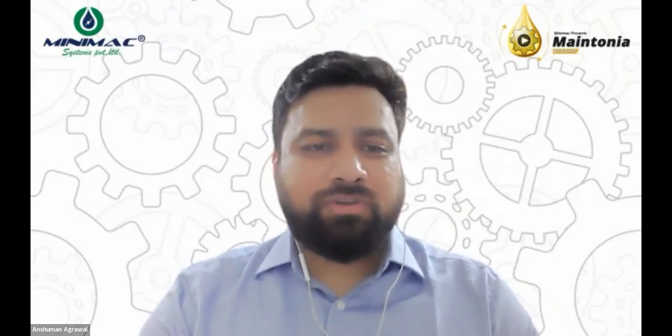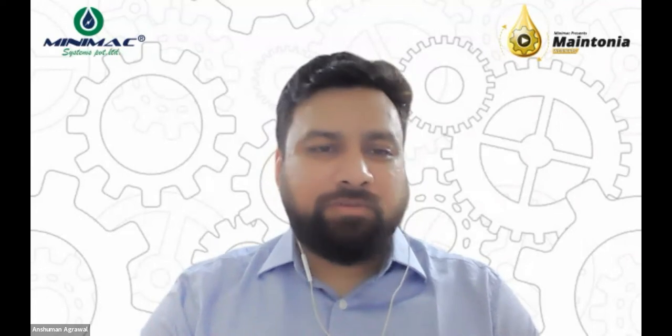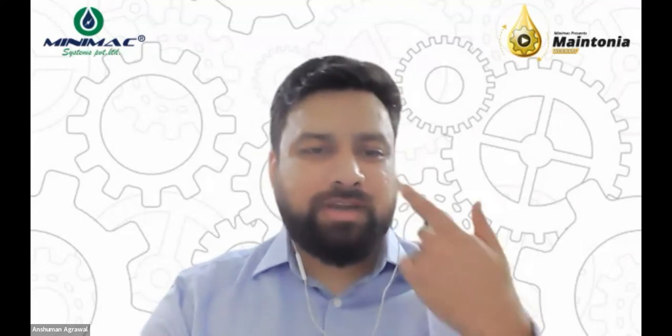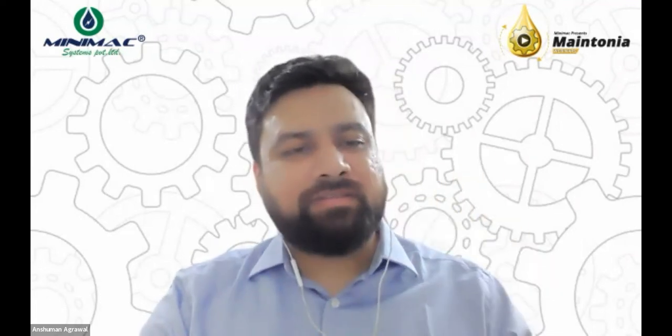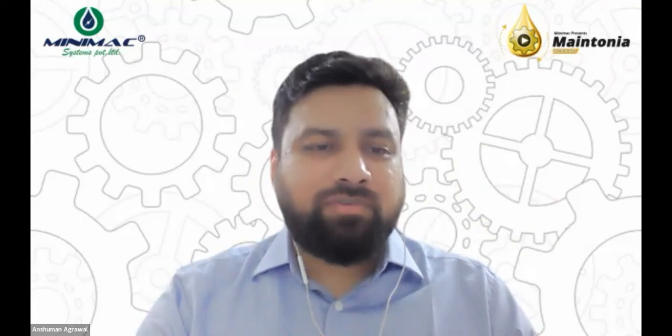Okay, let's move on. Which of the technologies is best suitable for removal of dissolved water from oil? Certainly, it's the low vacuum dehydration once the oil already has dissolved moisture content. But as I mentioned, we can avoid that dissolved moisture content in the fluid by having a dry nitrogen blanketing system for the tank head space. But yes, once the oil already has the dissolved moisture content, because of various humidity reasons and other sources, the best technology available right now in the market is the low vacuum dehydration system.